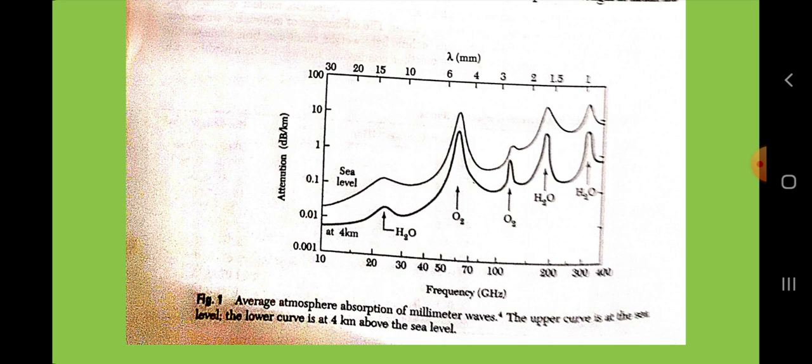So, at low microwave frequencies, resonant circuits can be made using inductive and capacitive elements. For millimeter wave and high frequency, however, the values of LC components at resonance are too small for practical implementation. Other methods for providing resonant circuits must be used. One popular solution is the resonant cavity, called the tuned cavity.